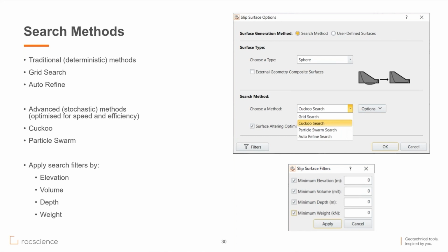The block files are lighter than common CAD geometry files. I guess it really depends on the size. From my experience, generating that model with 13 million blocks, to do that in a matter of 15-20 minutes would have been a lot faster using the block model import, as opposed to importing each of those material boundaries one by one and dividing all into a model.